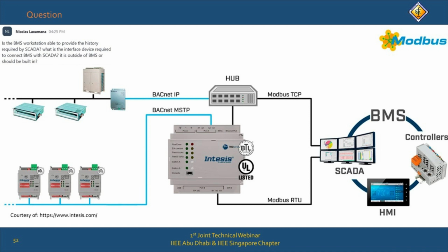Yes po, we can do it. As I have said during the webinar, in automation, everything is possible for as long as there are devices that can support it. In this case, one example that we can use is the product offered by Intesis. From the website that we can see here, they have a gateway that can integrate any BACnet or BACnet IP server device with a Modbus BMS or any Modbus TCP or Modbus RTU controller.